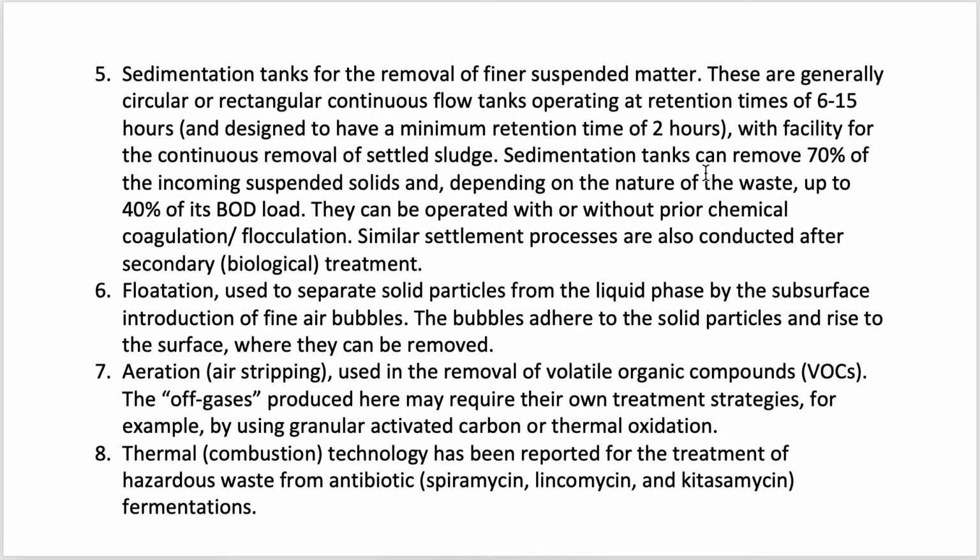Sedimentation tanks can remove 70% of the incoming suspended solids, quite an efficient process, and depending on the nature of the waste, up to 40% of its BOD load. That's actually big. They can operate with or without prior chemical coagulation and flocculation. Sometimes coagulation or flocculation is done first, then the effluent flows through the sedimentation tank, or sometimes the effluent flows through the sedimentation tanks before coagulation or flocculation.